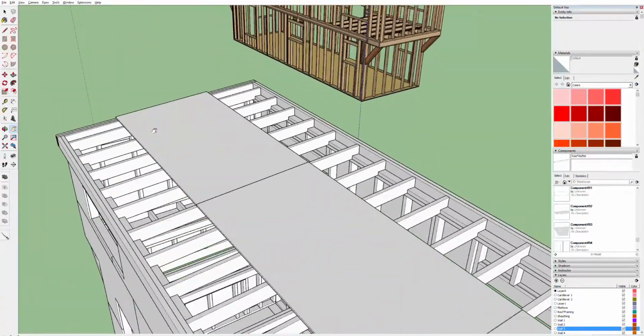Now, making these are going to be super easy. So let's just grab this. We'll move this over, lock to the red, make a copy of it. I think red was the wrong axis. Yeah, if I lock to red, it loses that whole inference that I want to slide down on that 3.6 degree angle, so I'm going to nix that.